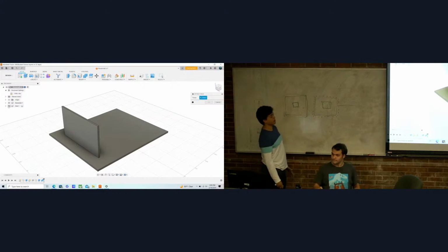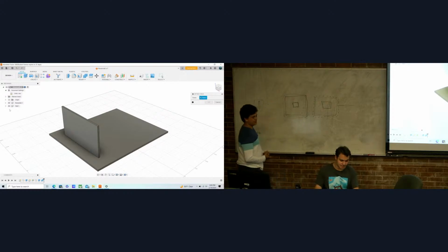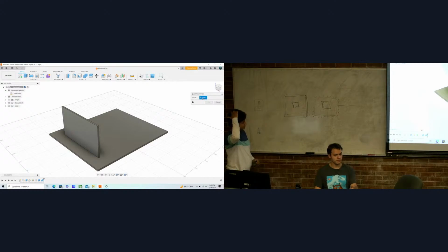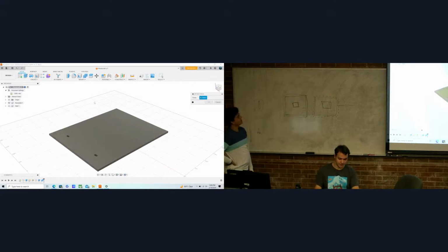That being said, if you took the exact same hovercraft design and had all of the pieces 3D printed instead, none of them would fit. You would have to go in and manually add offsets. Which gets us to the offset tool. If you were creating a piece that needed to be 3D printed, which you may actually have to do for your hovercrafts, there's the offset tool in here.